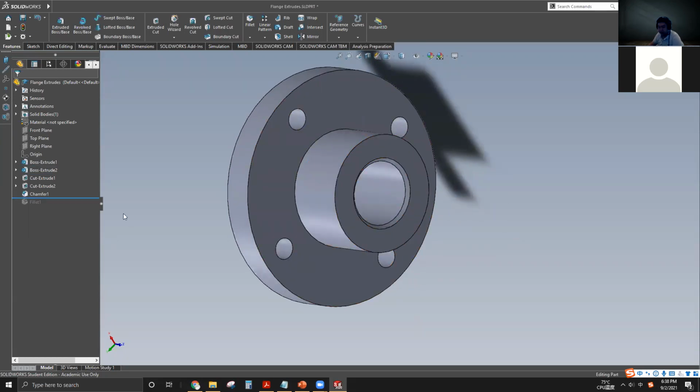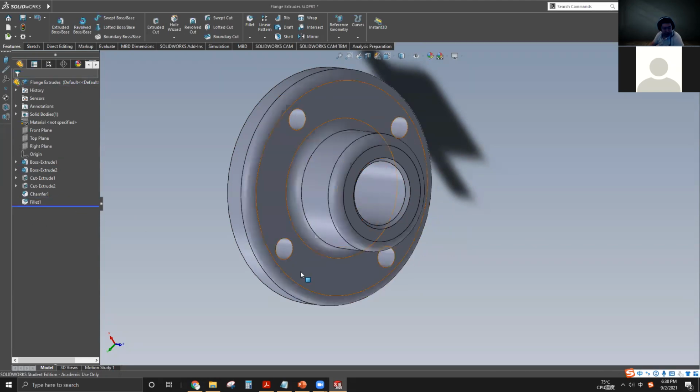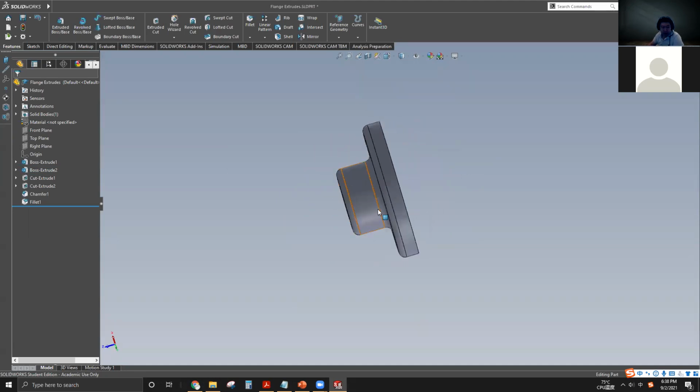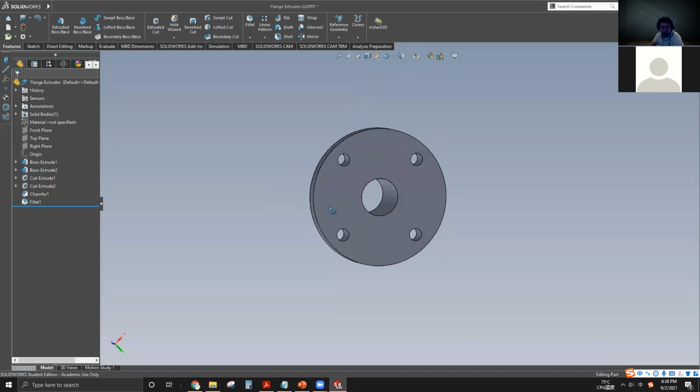Sometimes if you have either interference fit or have a really tight tolerance with your shaft, you want to put a chamfer, so when they install the shaft, it won't break the shaft edge. And the fillet, overall, just to remove sharp edges. So this is some nice thing to have when people handling this part, won't get hurt. Okay.